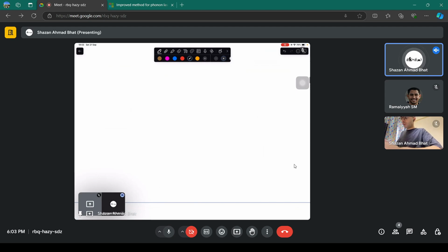In the previous session, we talked about a MOS capacitor. A MOS capacitor is something where you have a metal, an oxide and a semiconductor, which may be a p-type or an n-type semiconductor. If you stack them like this, you get a structure called metal oxide semiconductor. CAP stands for capacitor. There are some intriguing properties of this device which we studied.